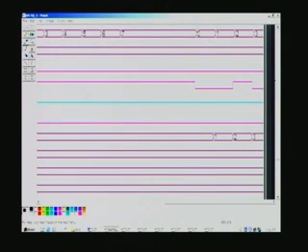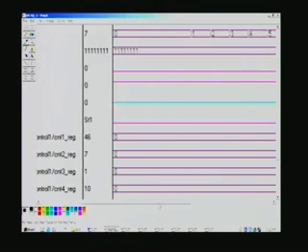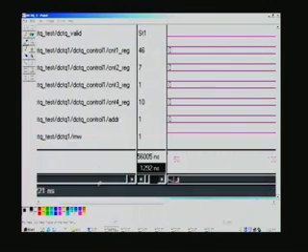So, corresponding to this 0, you can see this is also 0 here. This is nothing other than counter 1. So, these are the different counters we had used for keeping track of the pipeline, and so you would notice, let us just remember when this 0 starts, and that corresponds to say 185 nanosecond here, right at this point, and simultaneously at the same point R and W also switches control from 1 to 0, so that another RAM can be written here.